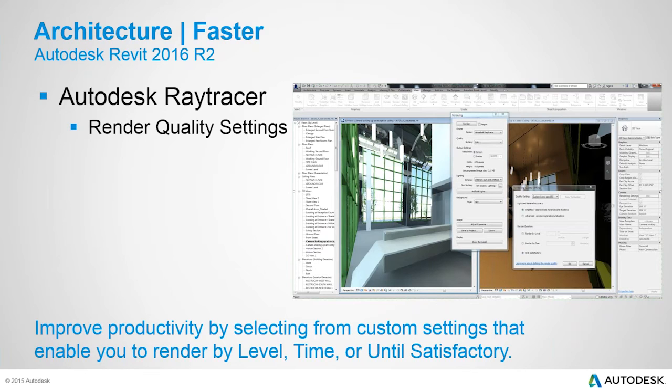So this is some of the power that's come across from 3D Studio Max, I suspect. When we select from the custom settings that enable you to render, you can now choose to render by level, by time, so you can set a time setting to say, right, just render this for 15 minutes or half an hour, or until satisfactory.